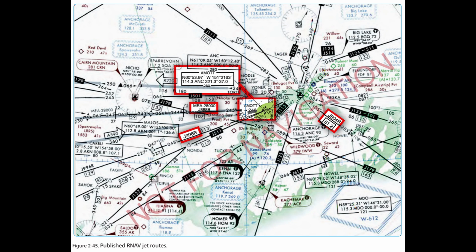Pilots flying aircraft that are equipped with latitude/longitude coordinate navigation capability, independent of VOR/TACAN references, may file for random RNAV routes at and above FL 390 within the conterminous United States using the following procedures. 1. File airport-to-airport flight plans prior to departure. 2. File the appropriate RNAV capability certification suffix in the flight plan.